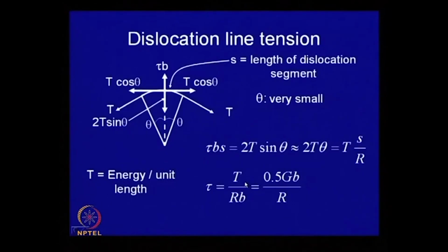Now, one source which we will talk about is this: suppose these dislocations are not necessarily straight, and the dislocation lines may be curved, and this extent of curvature will depend on the magnitude of the stress that you apply. And it is possible to derive a relationship between the applied shear stress and the radius of curvature of the dislocations, which is shown over here.